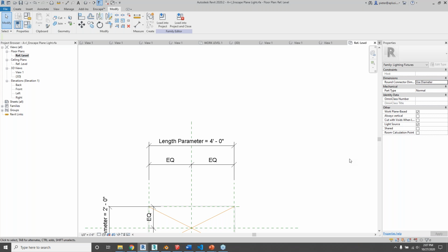Frosted glass, I will say, in the Enscape asset editor, which has the native Enscape material editor, there's actually a checkbox for frosted glass. So there it's really easy. In Revit, what we've been doing is putting a very dense noise map in the bump slot or in the glossiness slot or both. And that produces good effects. But it is pretty heavy. You want to have a decent graphics card for that.